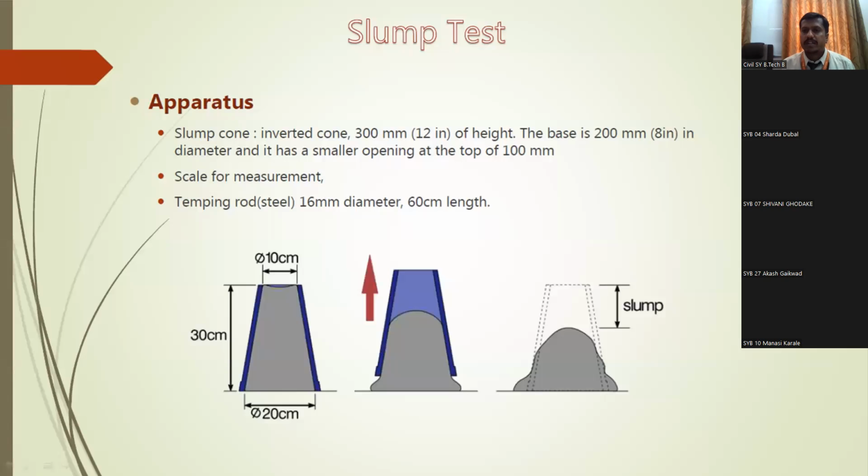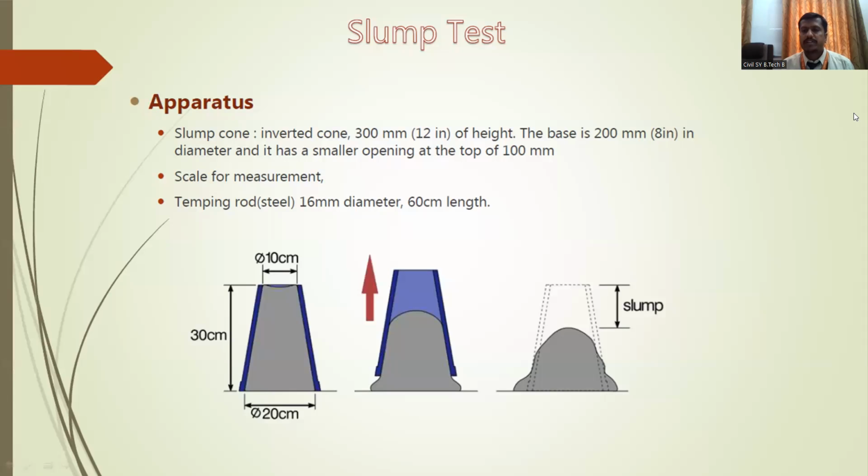As I told you, there is some unstable internet connectivity issue, that is why I got disconnected for a while. So, as I told you, you are going to take the difference between the two concrete heights. The first that you have poured is 30 centimeters initially, and the second one is nothing but the height of the concrete after collapsing. Okay, is it clear?